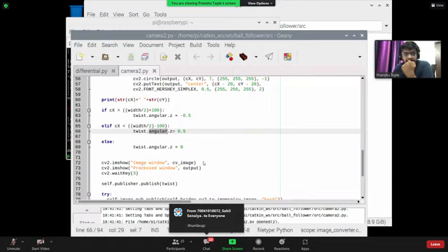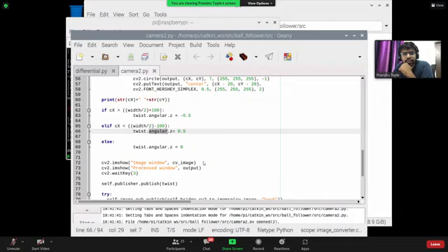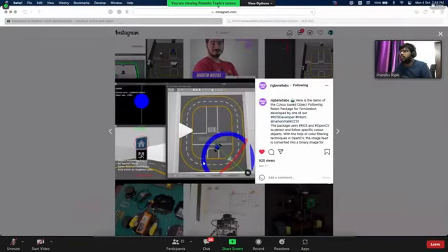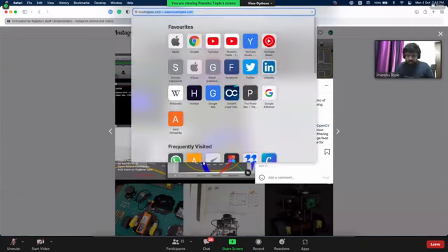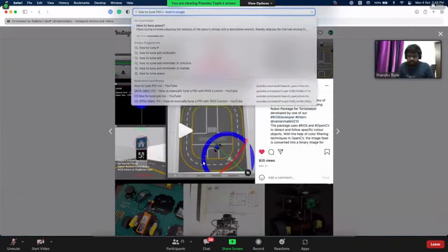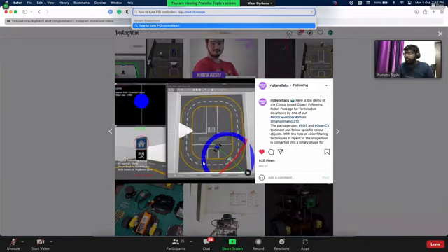Any other questions? Kamalnath asks, I have made a prismatic joint along Z axis, but whenever I launch Gazebo, it falls. So Kamalnath, you have to tune the controllers for that joint. There are tutorials if you search how to tune PID controllers in ROS.